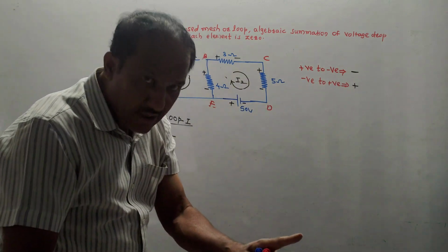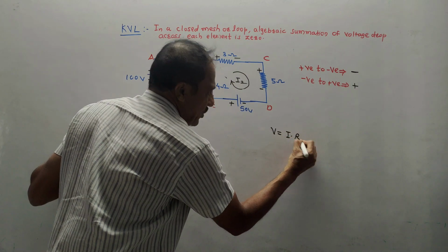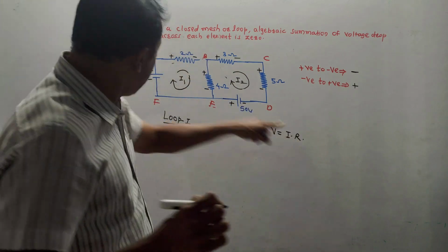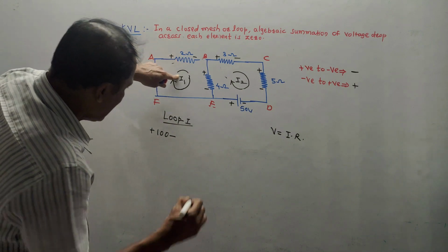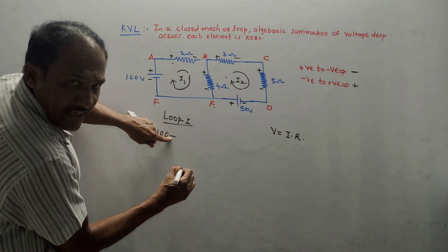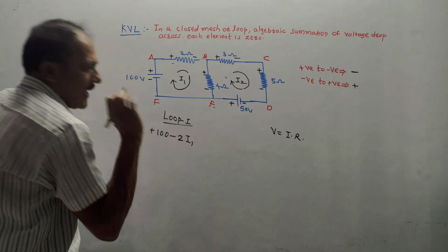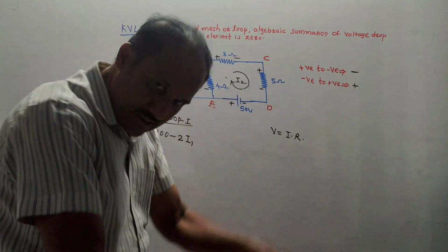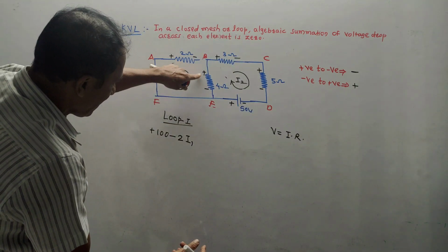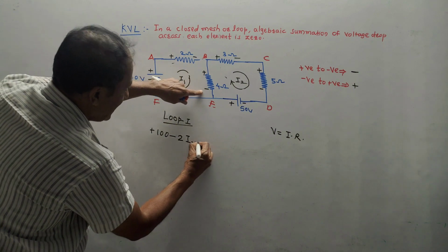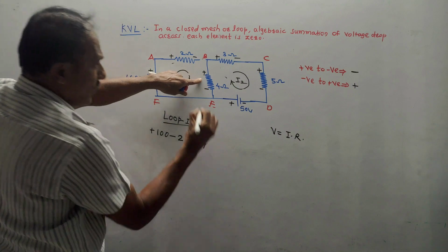For a resistor, write the equation like this. We know that voltage drop is given as I into R, that is current into resistance. Since this is a resistance, the current flowing through this is I1. I have already decided its sign is minus, so minus 2, the value of resistance, R into current I1. For a resistance, write the value of resistance into the current flowing through it. Now come back to this. Plus to minus is minus, so I will write minus, value of resistance 4.